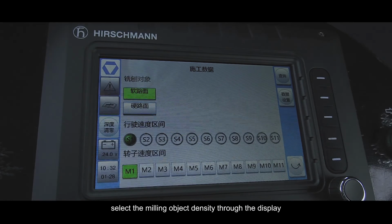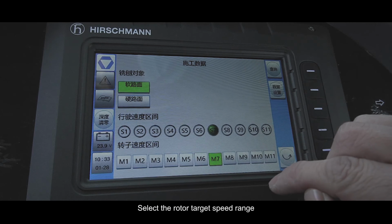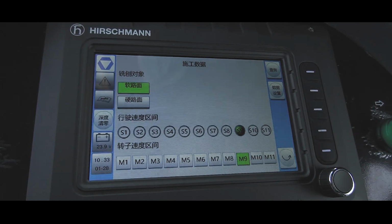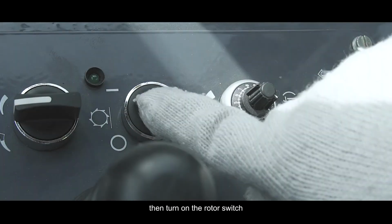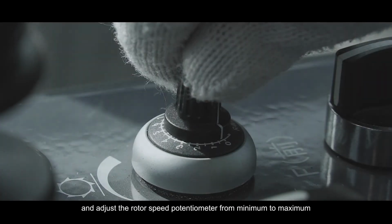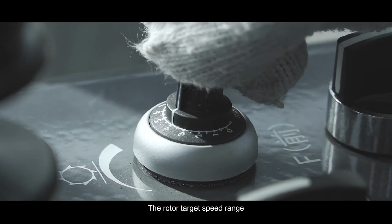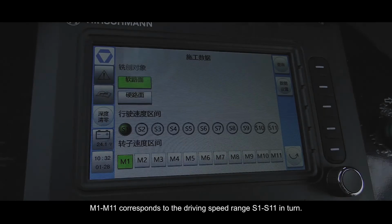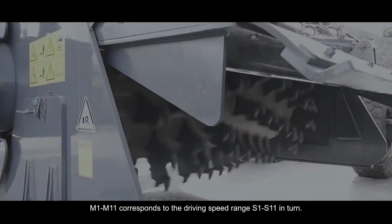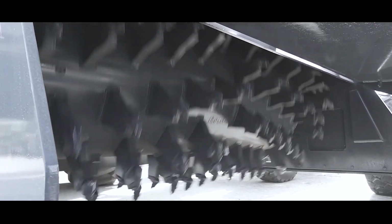First, select the milling object density through the display. Select the rotor target speed range, such as M1. Then, turn on the rotor switch and adjust the rotor speed potentiometer from minimum to maximum. The rotor target speed range M1 to M11 corresponds to the driving speed range S1 to S11 in turn.